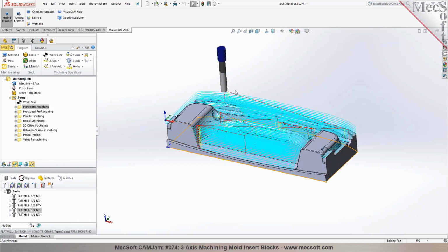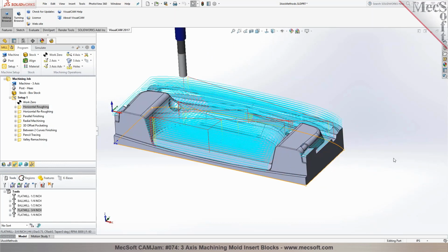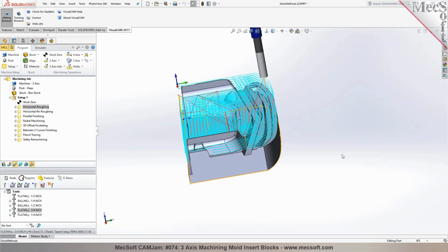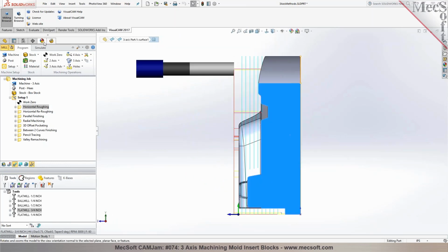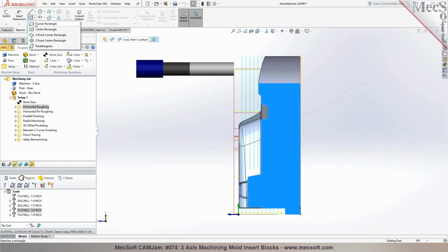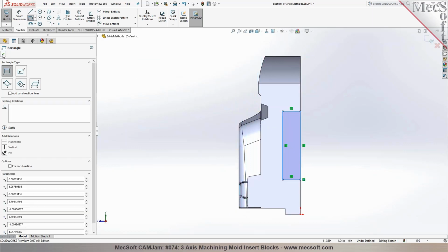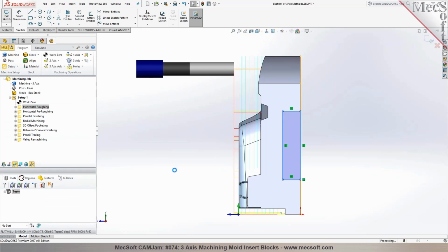Oh, yeah, no, so you would end up drawing that or pulling in some assembly. There's quite a bit available online, but you would pull that into the assembly, and then you have to save it out as a part from an assembly. So for example, I can say this is where my clamp is going to be. I can just put in a block that's slightly larger than the X, Y, and Z extents. So I can throw in a rectangle, and then I can extrude this to represent my clamp. I'm going to do an extrude boss, pick that sketch right here and say this is where my clamp is going to be.